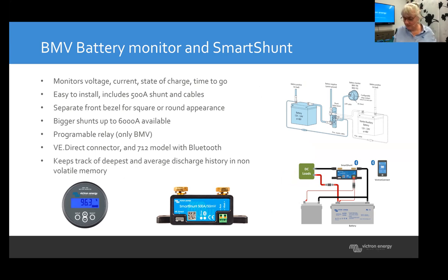You can actually see them on the shunt, so there's 2. So this is a shunt of a 700 with only 1 input. That's that orange thing there. And this is the shunt for a 702, which has 2 inputs. See? So what it can do, it can measure something extra, like a start battery, a midpoint of a battery system, or temperature. So there's some extra features. But the basic feature basically is determining the state of charge of the battery.